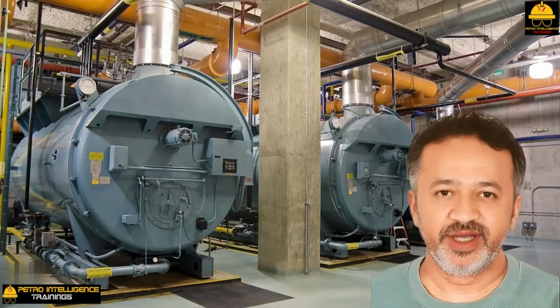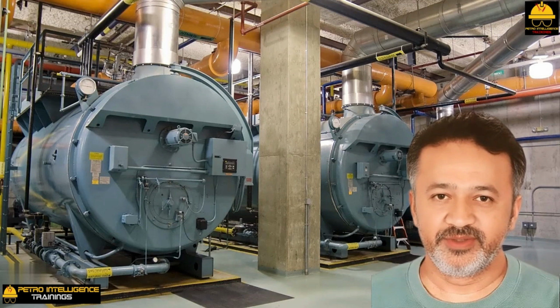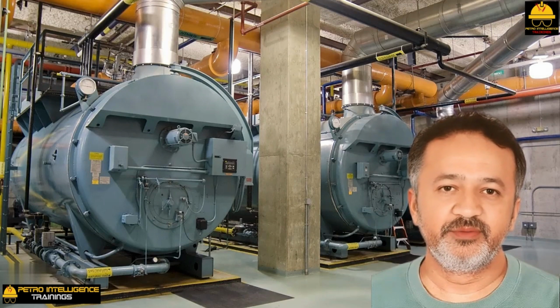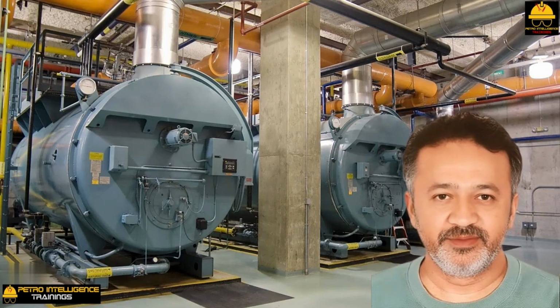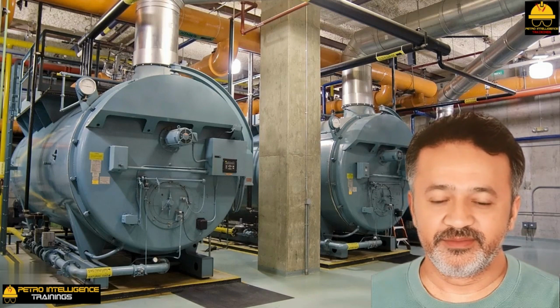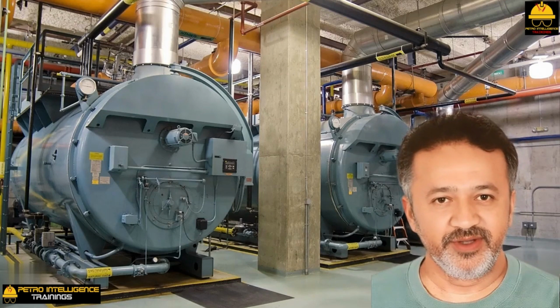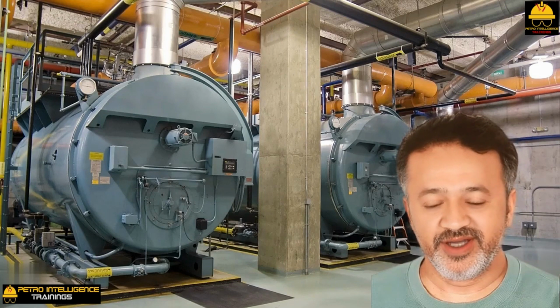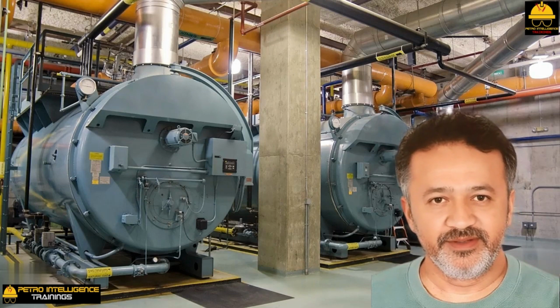Controlling steam drum levels. Ordinary level control does not work in steam drums or kettle boilers. The problem is the lower density of the boiling water as compared to the greater density of the non-boiling hot water in the external level sensing chamber. The boiling water will be at a 10 to 50% higher level inside the steam drum than the water in the level sensing chamber or gauge glass. There are two ways of dealing with this problem.